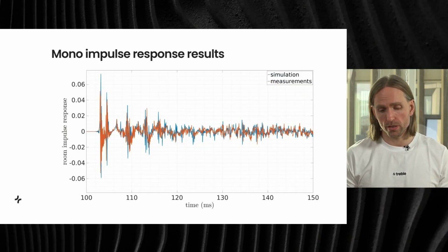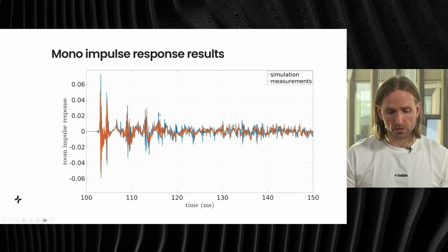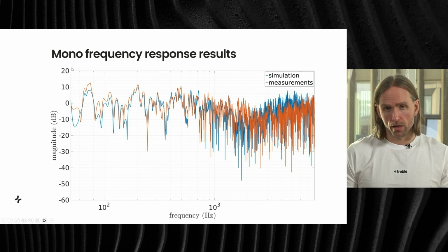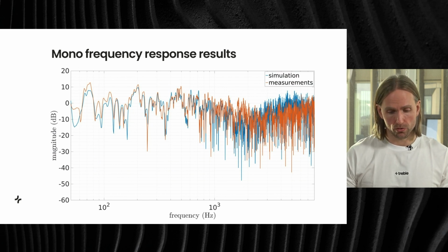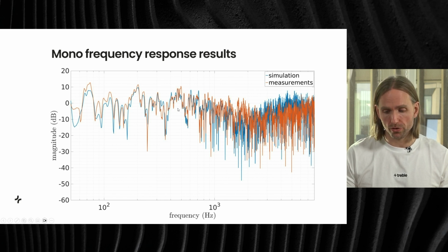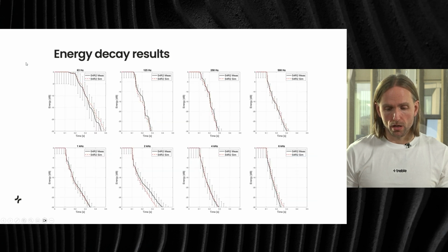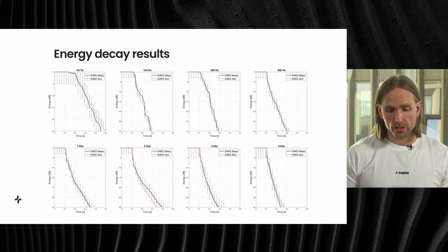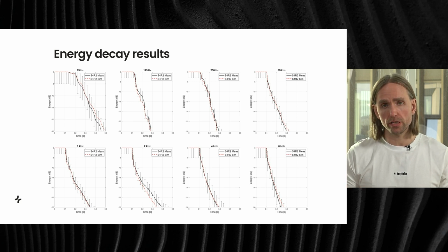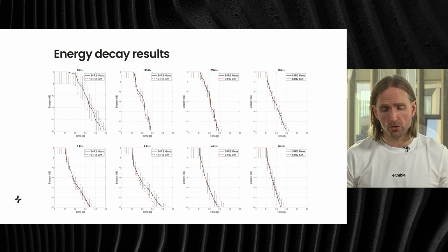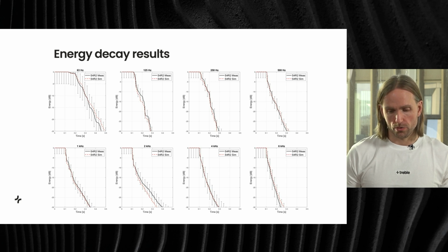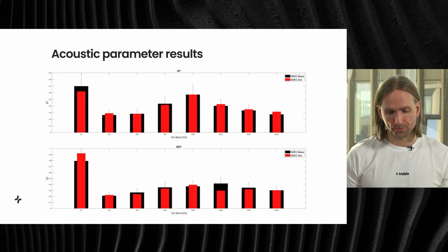excellent match between measurements and simulations. The early reflections are captured very nicely and the overall energy decay as well. If we look in the frequency domain, also a great match. The low to mid frequency modal behavior is captured nicely and the high frequency trend is also captured very well. Energy decay at different frequencies looks very spot on. It of course helps that in this case we know the material properties of the wall materials quite well. So there's good input data into the simulation.